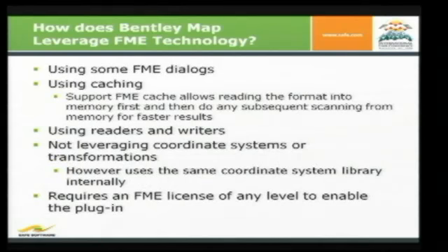Actually, my presentation is not going to be that long, but that's all right. So we're going to import a building shelf using CityGML. We're going to visualize the building data along with the 3D zoning. So that's going to be an interesting usage. Perform 3D smart editing. That's a tool we built inside BentleyMap. And export the adjusted result back to CityGML for consumption.